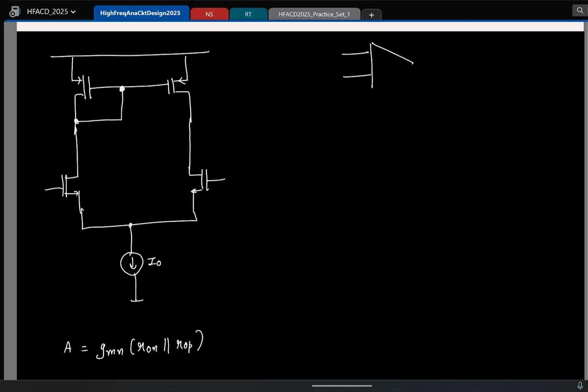So now we seem to have a candidate for making an opamp, and remember the opamp is essentially this fellow. And what kind of control source is an ideal opamp? Voltage control, voltage source. So if let us say this is V1, V2, the gain is A, the output voltage will be, let me write it here. V out will essentially be A times (V1 minus V2), right?